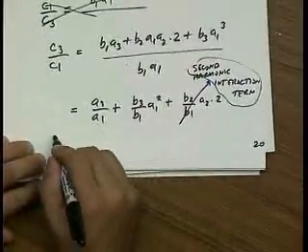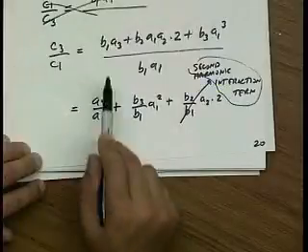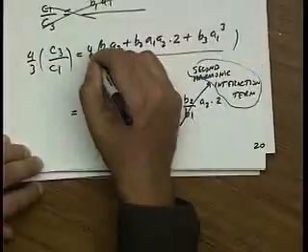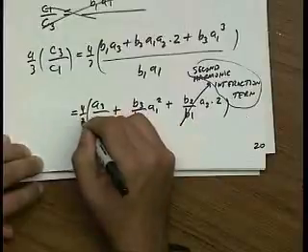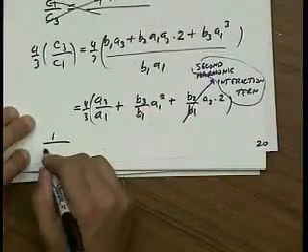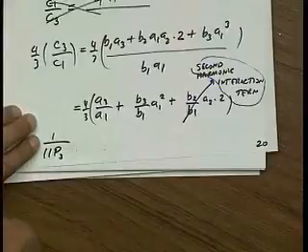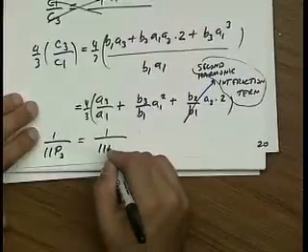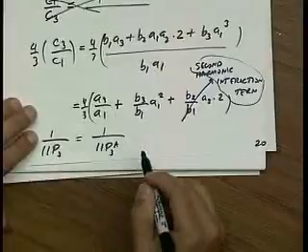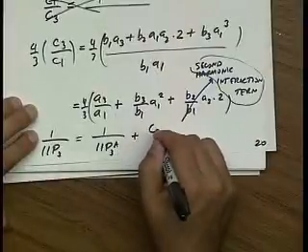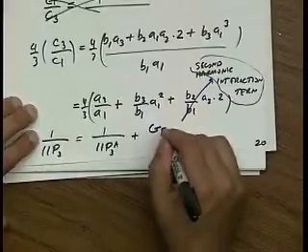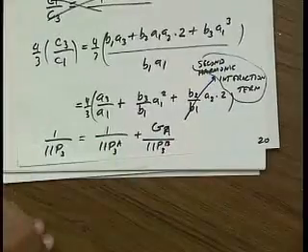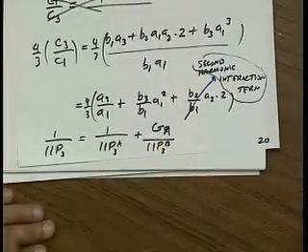So here, I can now write an equation. If I just multiply this equation by a constant 4/3, so I multiply here by 4/3, here by 4/3, and here by 4/3, I can write this as 1 over the input IP3 of the overall amplifier, the cascade, is equal to 1 over the input IP3 of amplifier A, that's this term, plus power gain of amplifier A, divided by the input IP3 of amplifier B. Okay? This is the power gain because it's the voltage gain squared.